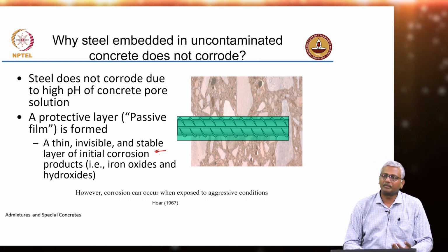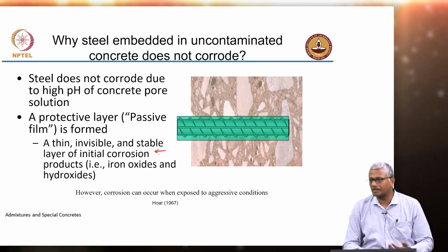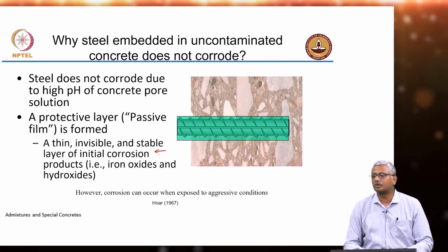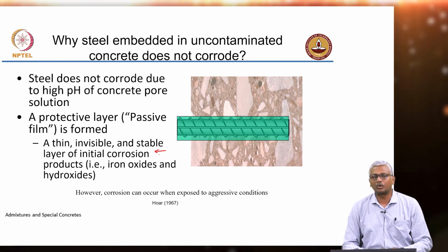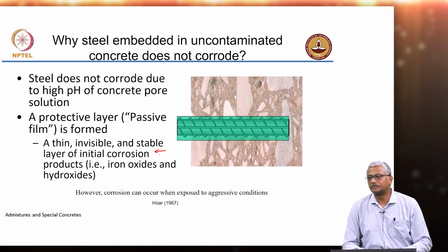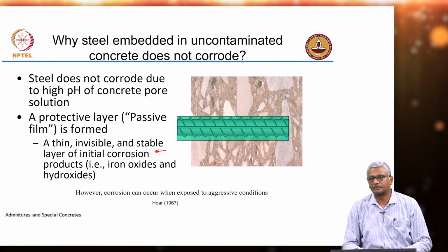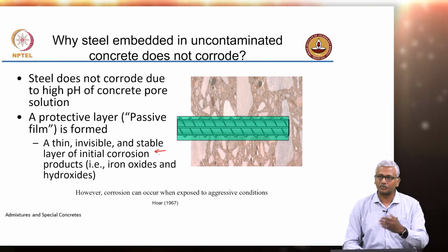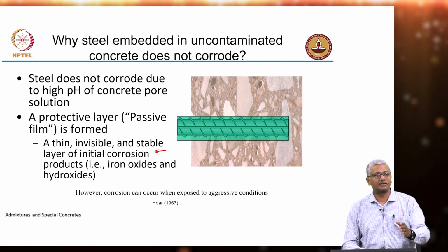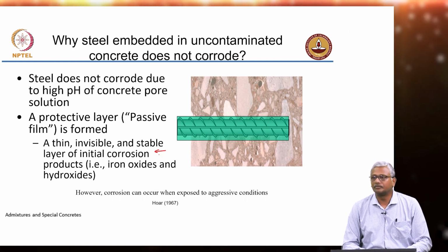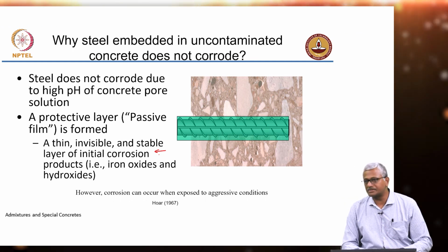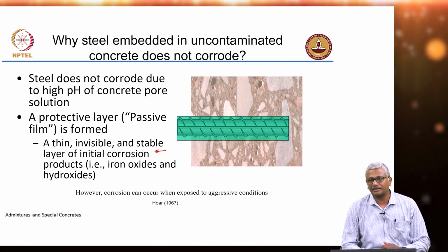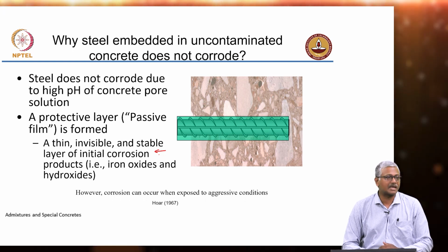Now, as you move from regular reinforcing steel to corrosion resistant steel or to stainless steel, what are you doing essentially there? What changes are you making to steel as it goes from reinforcing steel to corrosion resistant steel to stainless steel? We are adding some alloying elements, typically chromium or nickel, and these are enhancing the corrosion resistance capabilities of the steel.